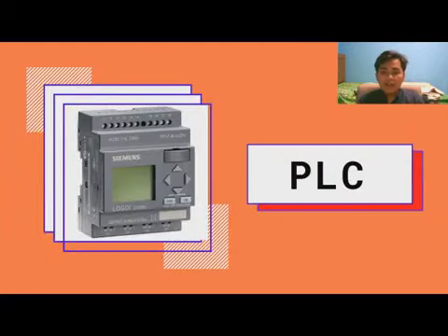PLC, or a programmable logic controller, is an industrial computer control system that continuously monitors the state of input devices and makes decisions based upon a custom program to control the state of output devices. Almost any production line, machine function, or process can be greatly enhanced using this type of control system. However, the biggest benefit in using a PLC is the ability to change and replicate the operation or process while collecting and communicating vital information.